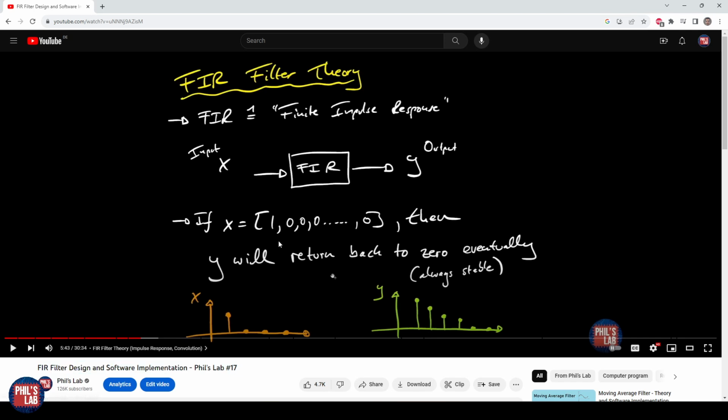So all we have to do to then simulate this impulse response, this guitar, cabinet, microphone, and speaker, is simply use the values we obtained from the time domain, pop that into an FIR filter structure, pass our input coming, for example, from a preamp, compute the FIR output, and the output is then our modeled or simulated output. That's really as simple as it is for this case. Of course, there are many different techniques you could use, but the simplest is an FIR simulation.